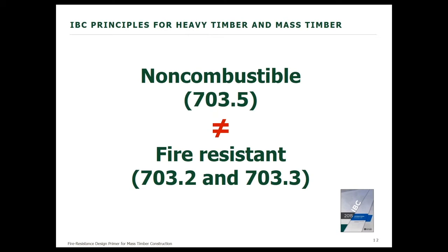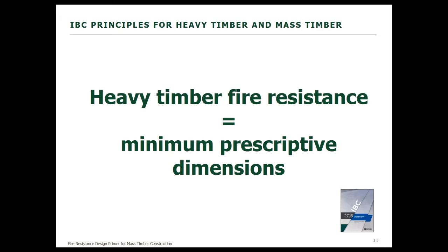Just so you can equate the temperatures that I referred to before, in the ASTM E119 fire test, a temperature of 1,000 degrees Fahrenheit is reached at 5 minutes, 1,300 degrees Fahrenheit at 10 minutes, and 1,550 degrees Fahrenheit at 30 minutes. That means that shortly after 5 minutes, the steel is at 50% strength and 10% strength after only about 12 minutes.